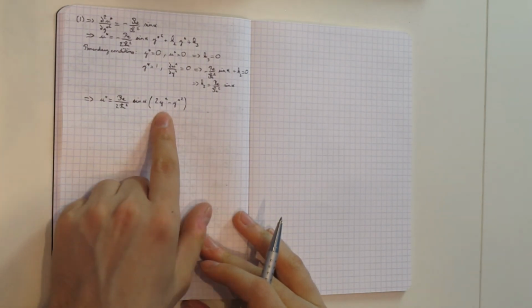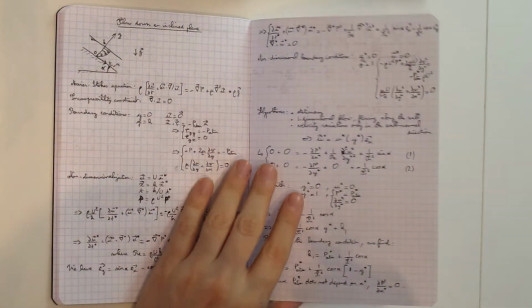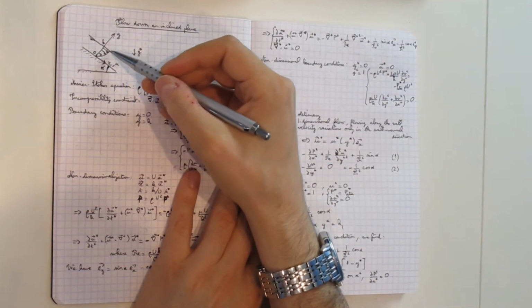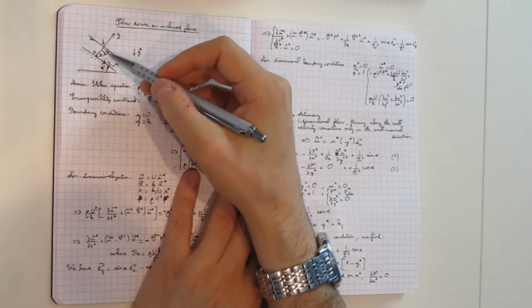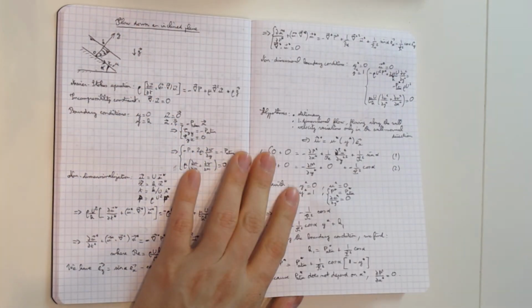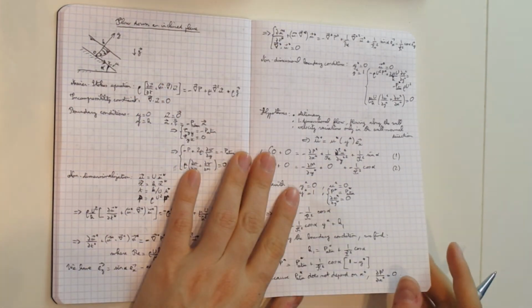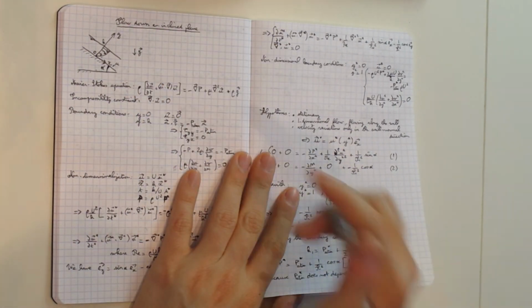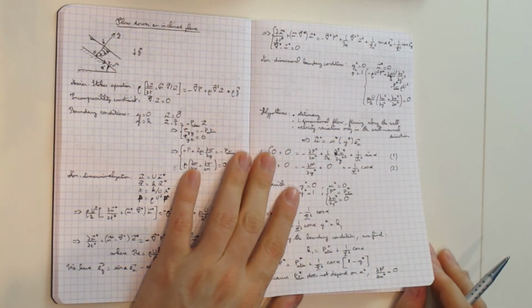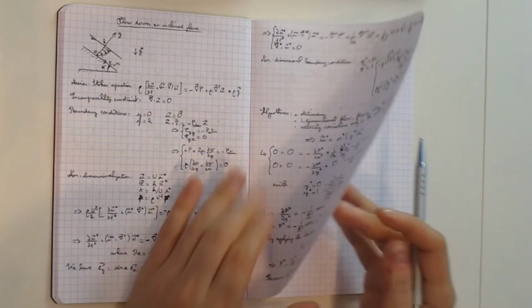Of course, it's 0 at y equals 0, and it had to be maximum at y star equals 1. So we do have that quadratic, parabolic profile here, that cuts here where there is no further increase at the point where the velocity is maximum, or in which there is no more velocity increase, because that free surface supports a free stress boundary condition, which we wrote here.